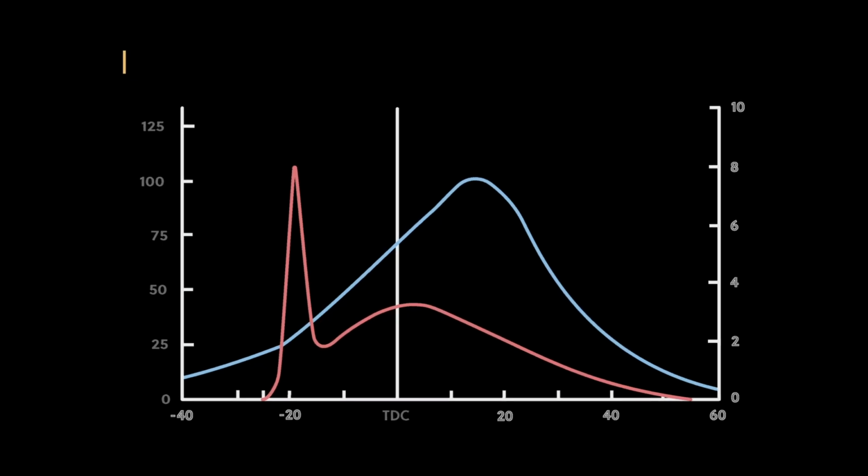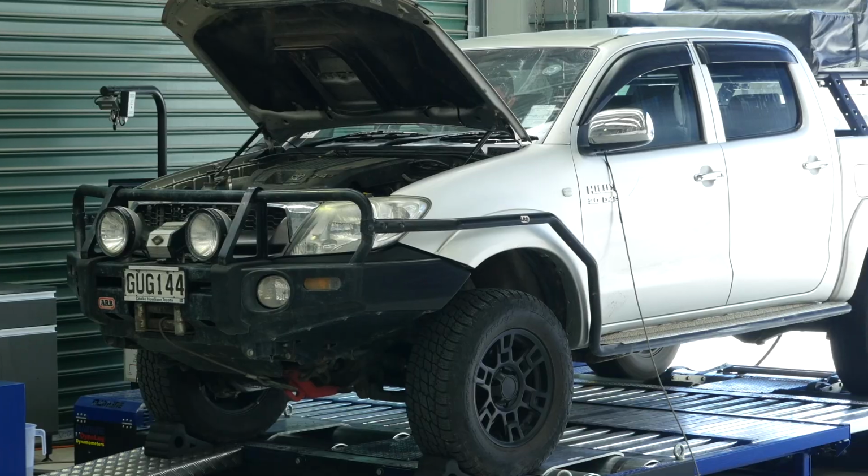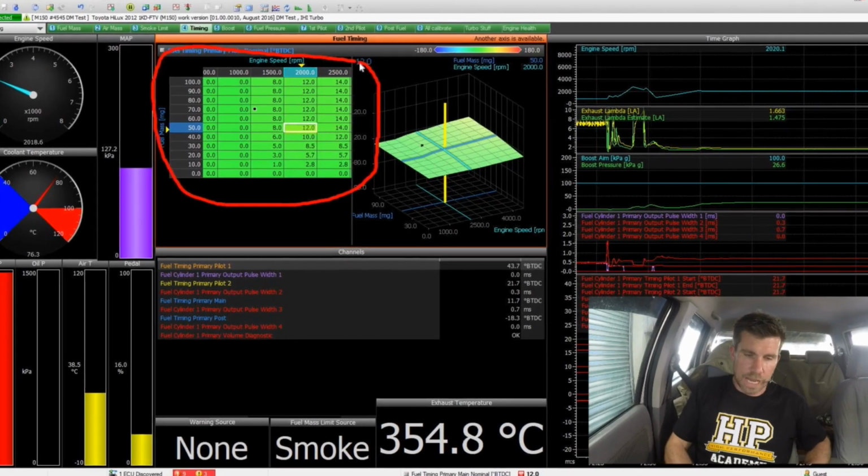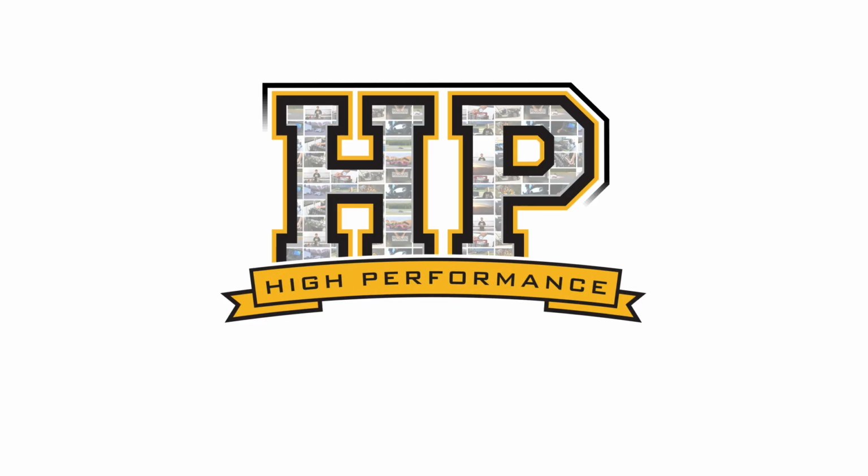Welcome along to this webinar where we're going to be discussing the subject of measuring exhaust gas temperature, or EGT, in a common rail diesel engine. Now first of all, we're going to start with why we would want to monitor our exhaust gas temperature. And really it's not the exhaust gas temperature specifically that we're interested in. What we're trying to do is get a bit of a feel for what's happening inside the combustion chamber. What we're really interested in is the combustion chamber temperature.